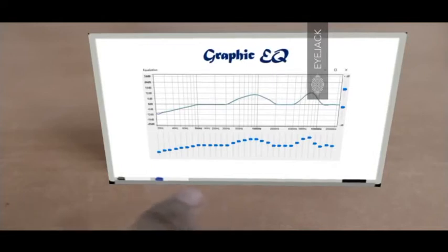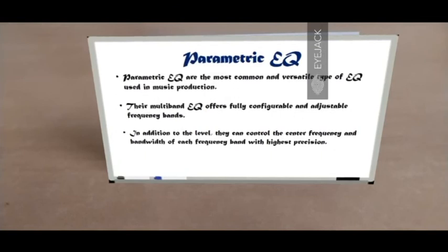And that's where the parametric EQ comes into play, which is very useful for professional level audio editing or audio mixing. In this example, I've used the graphic EQ to change the frequency spectrum. I've applied a bass cut filter below 100 Hz. Then I've boosted the frequencies in the range 300 to 2000 Hz and also some range in the treble region. Let's talk about parametric EQ.